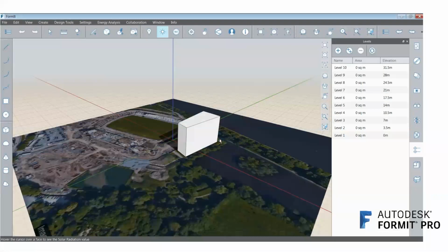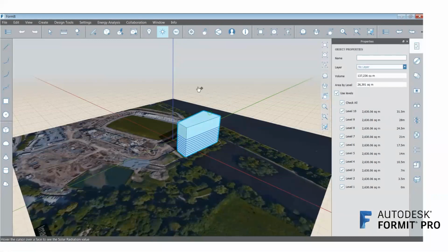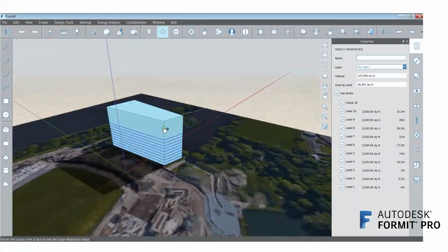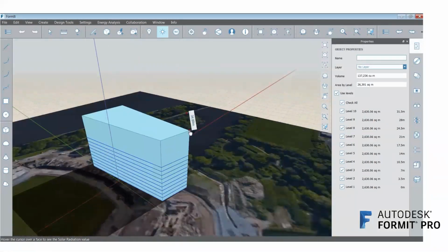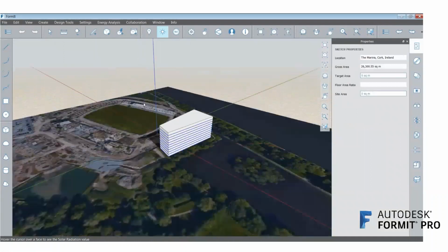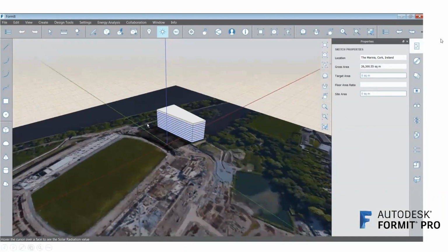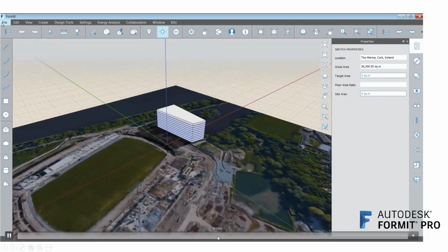And you can also attach levels to this as well for when you're looking to import it into Revit, this is where that becomes fairly relevant. So you can see here, I've just created the levels. I've just pulled it down to 10 stories. I can set any distance between those as well. And now I'm just going to speed up the video here. I can then import that into Revit.